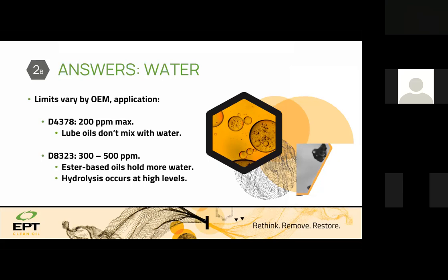They have a characteristic that they can absorb water from the moisture around them, the air around them, and they have more capacity to hold. But once it comes in, it reacts with the structure of the synthetic, and the chemical reaction which happens is called hydrolysis.